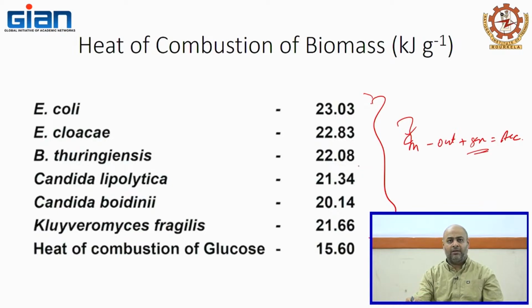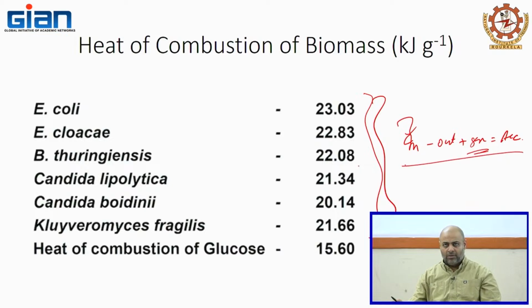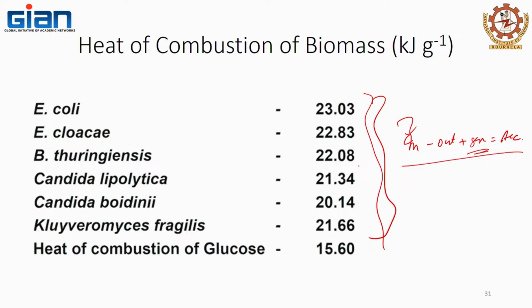Generation can be from the microbes. That will lead to the change in the temperature with respect to time. So when you do that particular balance, you can take into account all the heat sources which are going to add to the system. Because its generation is adding to the system, it is positive; if it was removal of heat, there would have been a negative value, right? That's how simple it is.